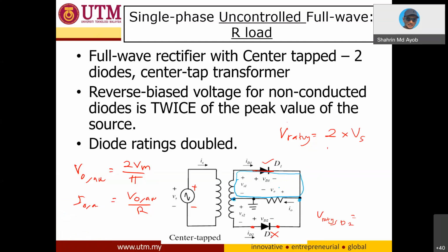So you have two voltages here. When you put a voltmeter here, you will have V out and Vs. So this one is V out 1 plus Vs, where V out 1, when it is turned on, is Vs, and then plus Vs. So meaning that you have two Vs. So your V rating should be equal to 2 times the voltage supply.